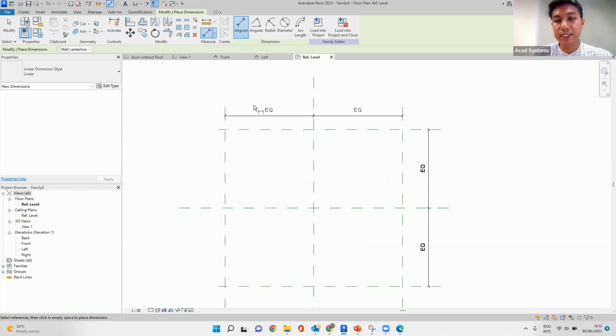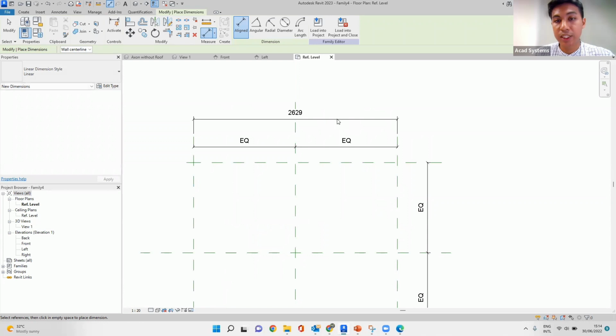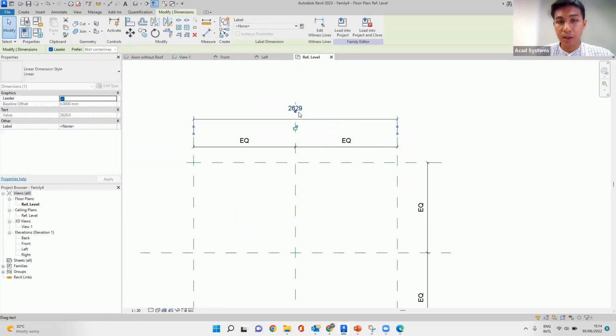Now I want to set parameters to it. You can actually draw the geometry first or add in the parameters. These two you can do depending on your preference. I would like to put the parameters first in this case. So again, I click on the measure on this reference plane to this reference plane. This dimension, I will not change it first. Click on it and then click on create parameter here.